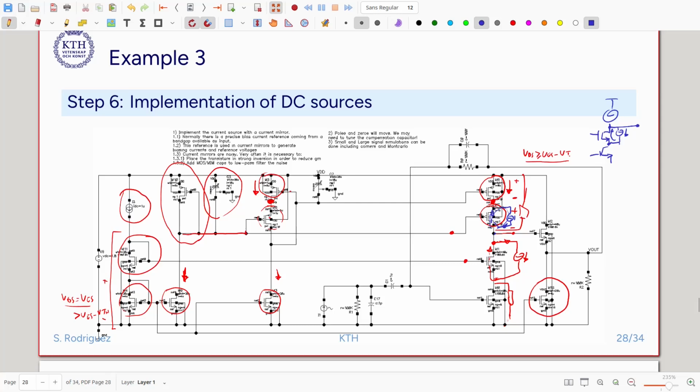However, at very high frequencies there is a capacitance here to the bulk, and then some current starts passing in this direction, and then this cancellation doesn't work anymore. So when the frequencies start going up, part of the current flows through the load and then produces a noise at the output. So at very low frequencies the cascode does not contribute with noise, and just when the frequencies start becoming very large, we see some noise contribution at high frequencies.